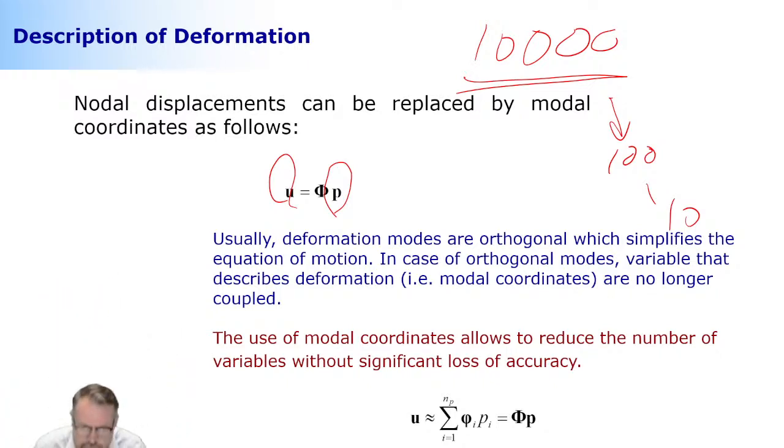Like if you have an element like this, this is a beam structure. Each of these are nodal locations. One of the different ways could be that this node here is only moving here and the rest are staying where they are. This is hard to see happening in reality. It could, but I don't think it is going to be very important. Or let's say that this one here is moving a little bit in this direction, others are staying where they are. Again, I don't see that happening much in reality. So some of these modes are less important for us.